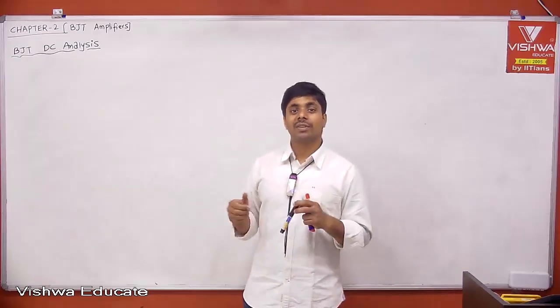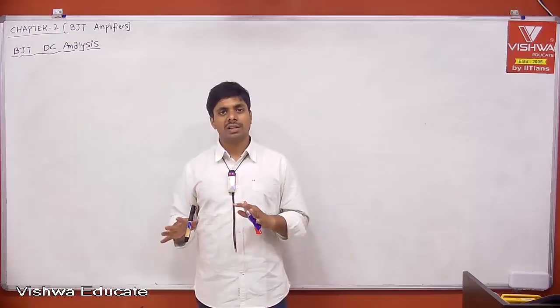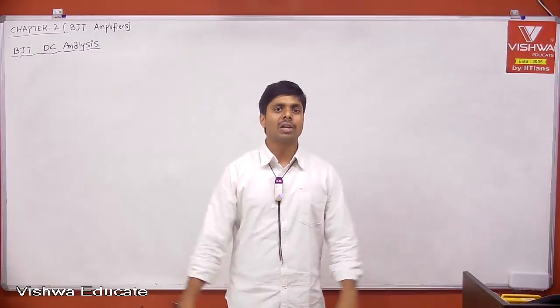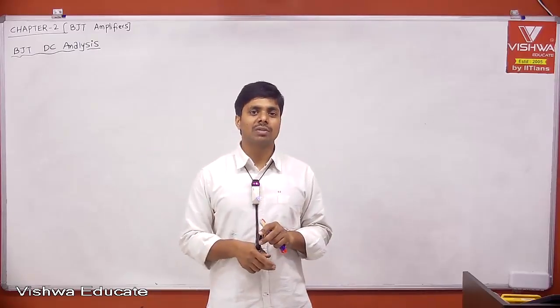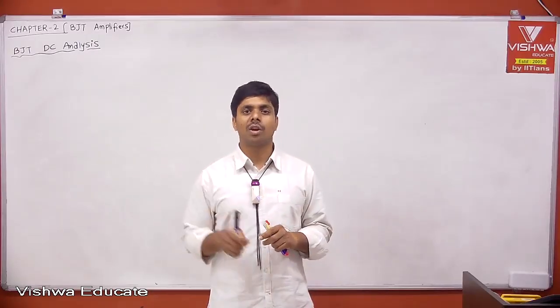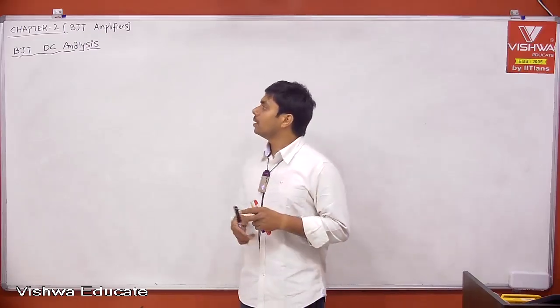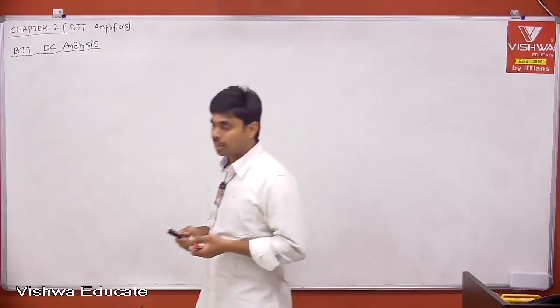But who is taking care of keeping the transistor in active region? If the transistor is in active region, then whatever analysis we did till now, the AC analysis and the calculated AC parameters, they are valid. For example, if the transistor is not in active region, whatever analysis we did, they are not correct. Therefore, whose job is it to make the transistor be in active region? DC analysis.